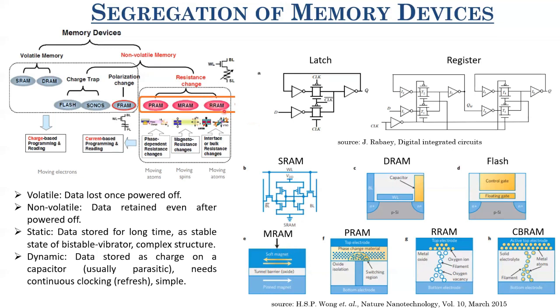Now we look at the other case, which is called RRAM or resistive RAM, or OXRAM is also a name for it. So there are different flavors of OXRAM, RRAM, or even memristors. These are also called memristors. So what are the different flavors? Typically you have these OXRAMs and you have these conductive bridge RAMs. So what are these OXRAMs?